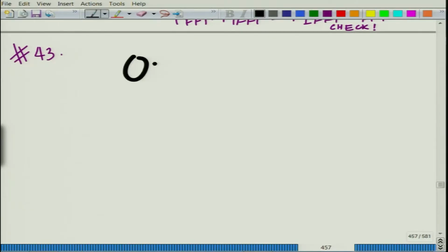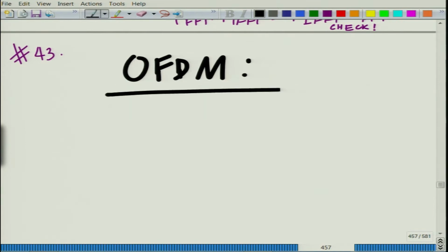in your laptop, right. So, OFDM is the dominant modulation, or one can call it the physical layer signaling strategy, that is employed in most modern day wireless communication systems. So, let us try to understand this better and see what is the relevance of the FFT and IFFT operations that we have just studied in this context. This is again a very interesting and very relevant application of the IFFT, and to begin with, OFDM is